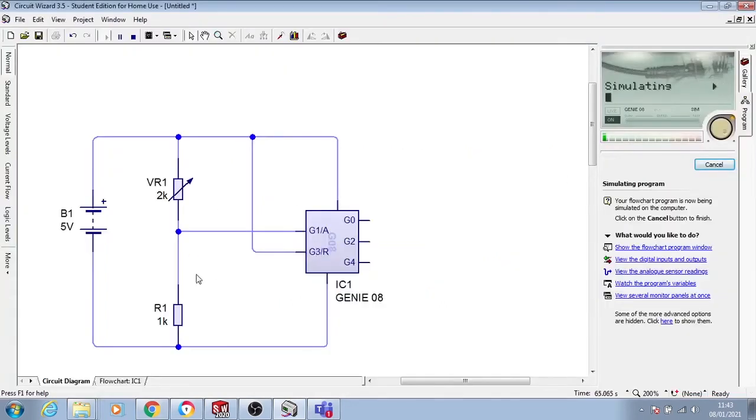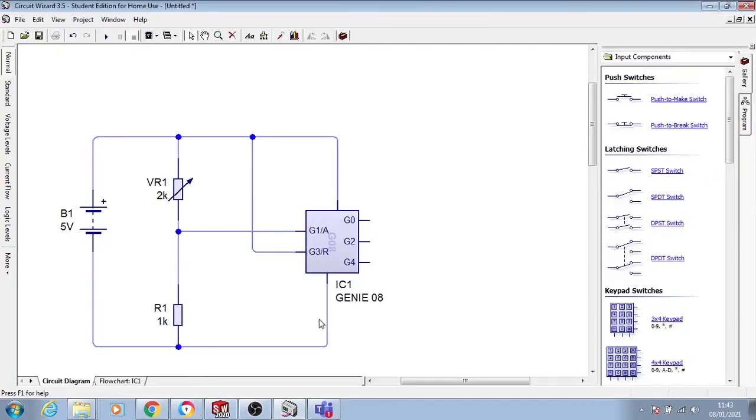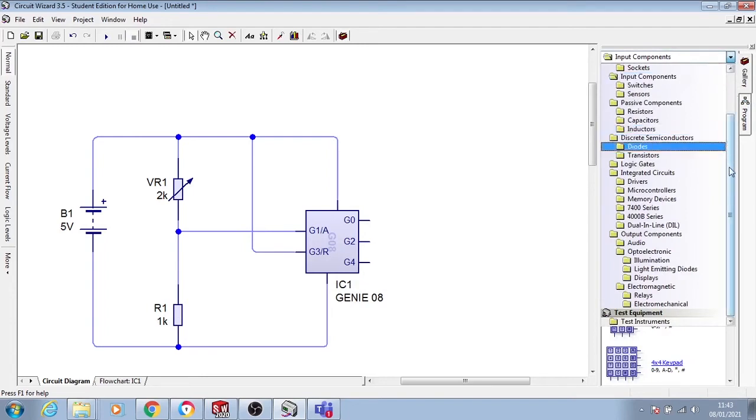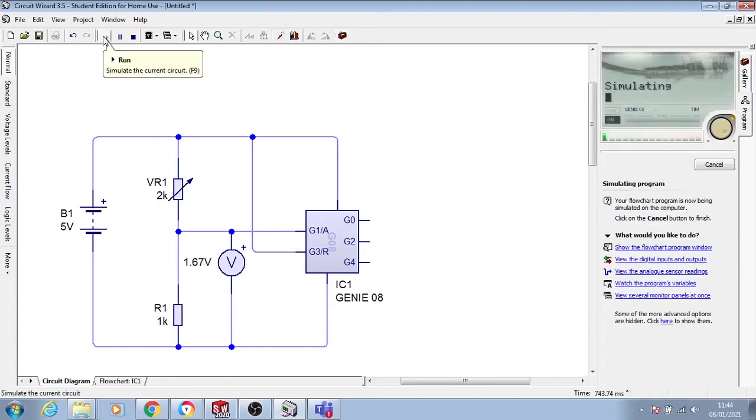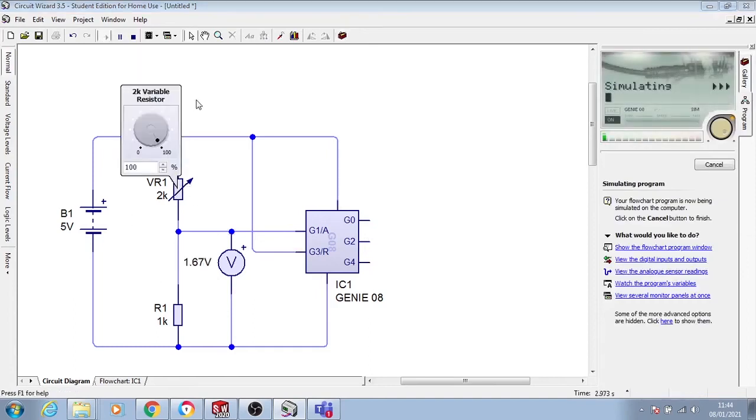And that's pretty much it. So a simple circuit design here that you can test. You can also put test instruments in here, rather than holding the mouse over. So we could put a voltmeter across this. So connect it from, this is the same as a 0-volt rail, and this is the 5-volt rail. We can see what that voltage is compared to 0. So you'll see whenever you play around with this, you can do it live and it will just change what the voltage is.